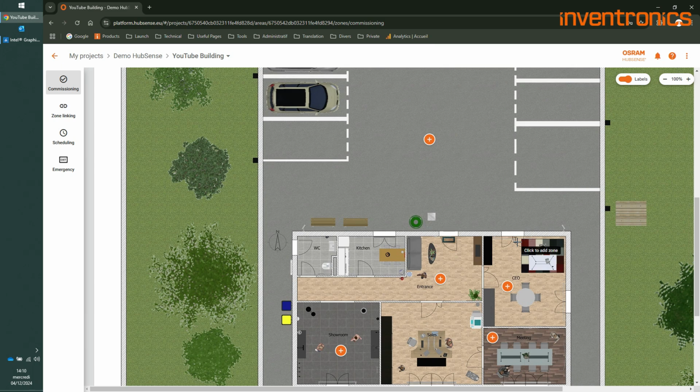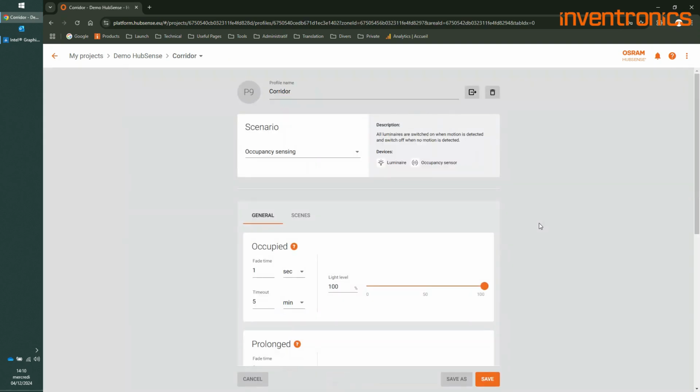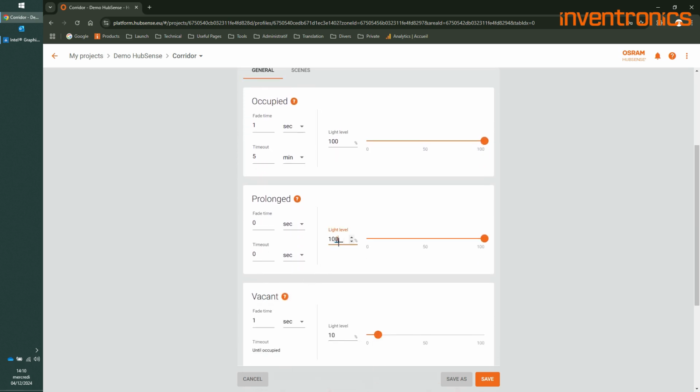Now that we know how each zone works, it's possible to adjust the settings. In the entrance, for example, to say that I want, 5 minutes after the last movement, a gentle reduction of the lighting to 23% for 30 seconds, before a total switch off.